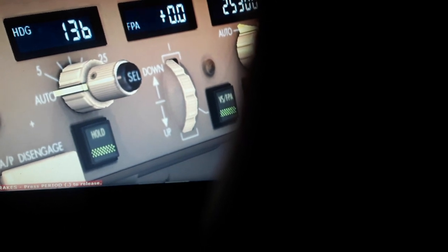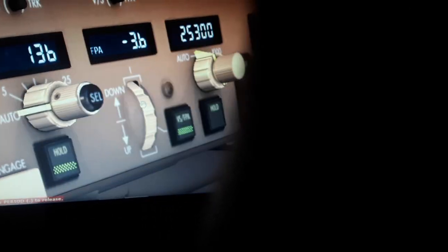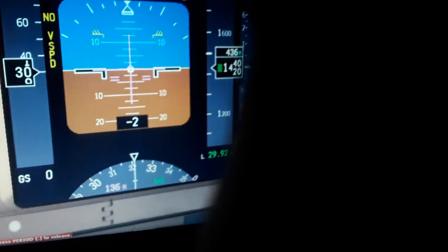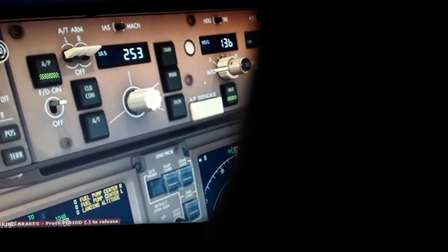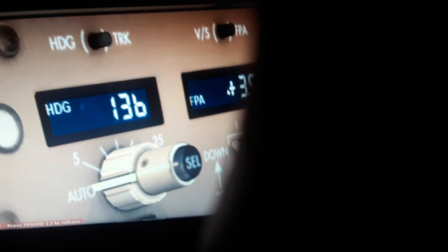We have also the vertical rate of climb and descent, the flight path angle. You will see the descent, the minus descent right now, minus 3.6. It will display over here. The purple lines, as you can see, below the axis in the flight director, and also the positive the other way up if you want to climb, 3.5 degrees up and down using this slider.